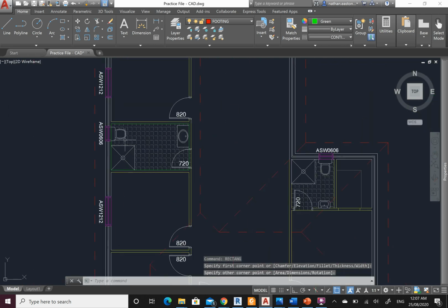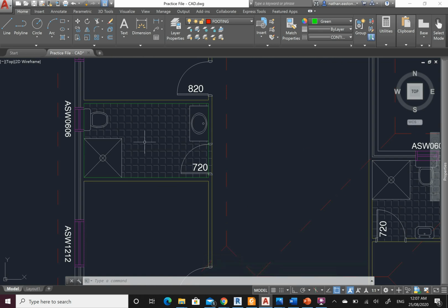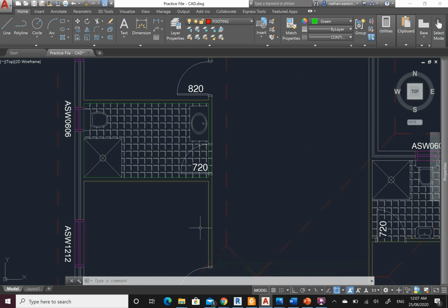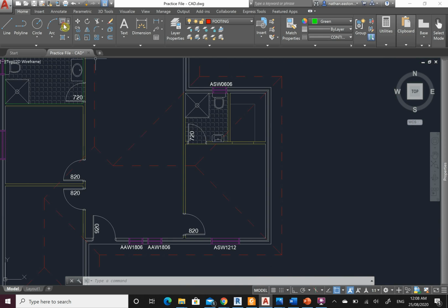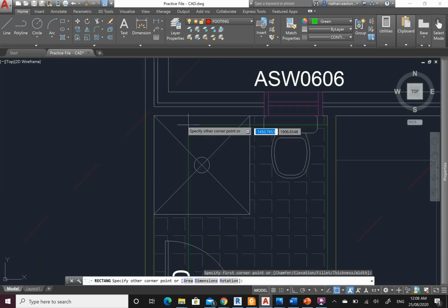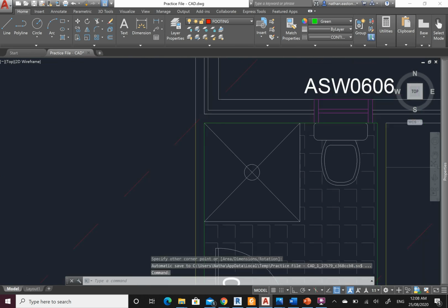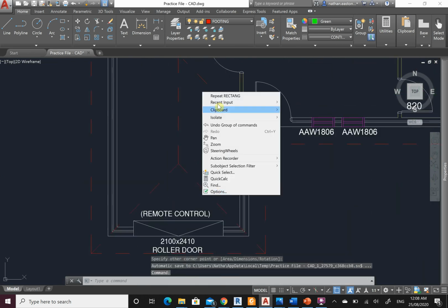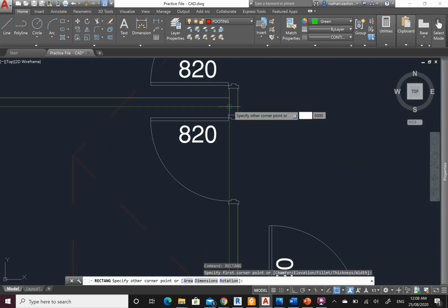So what happens is if this shower floods, we make this concrete inside sit lower than the rest of the house. So it gives us time. If it's flooding in here, the water's not going to come through, which means we sit the walls on the higher side. So the set down is 50 millimeters typically. There can be more, but generally it's a 50 millimeter set down. And the other one is the garage. So let's set down the garage to here.